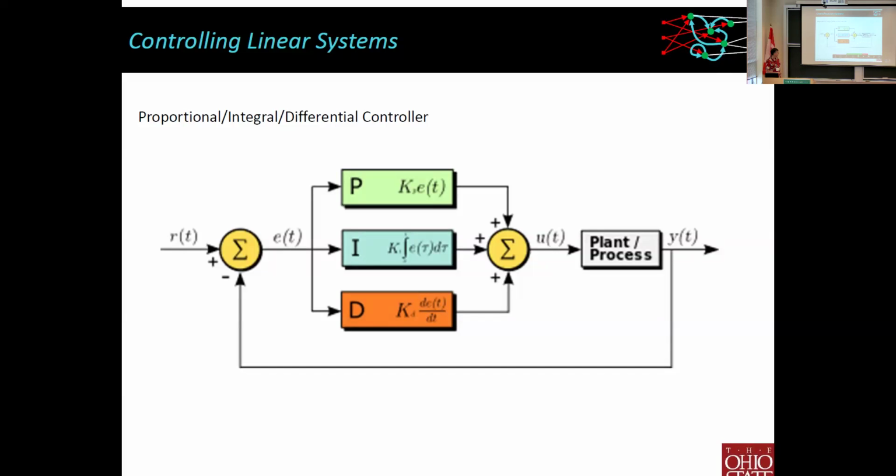And the problem with these PID controllers is that the plant may have very nonlinear behavior that we're familiar with in chaotic dynamical systems. The good part is that this is very simple. There are very well-defined rules for how you tune up these gains. You kick and perturb the system, see how the plant responds to those kicks, U of t, and then by analyzing those signals, that will allow you to set these gains. So it works great. It's very simple. It's computationally fast.